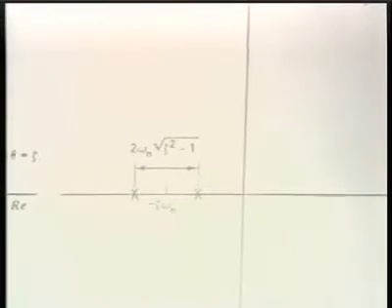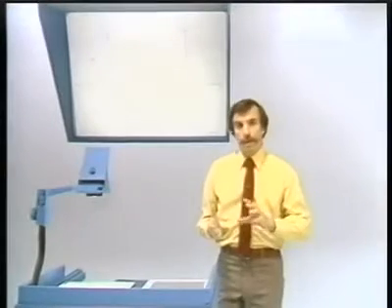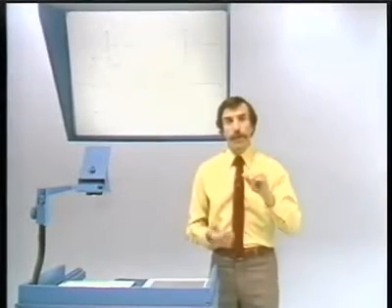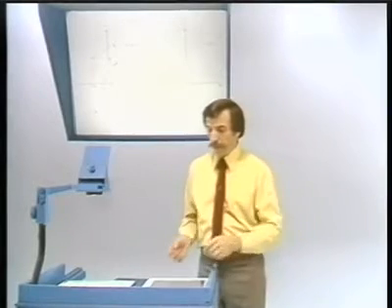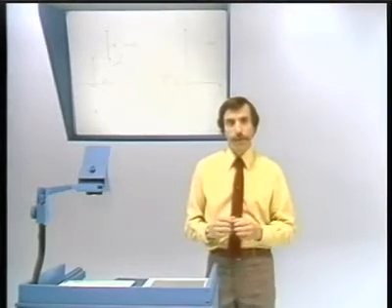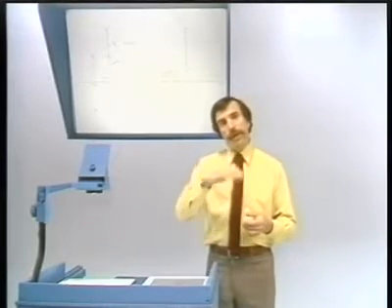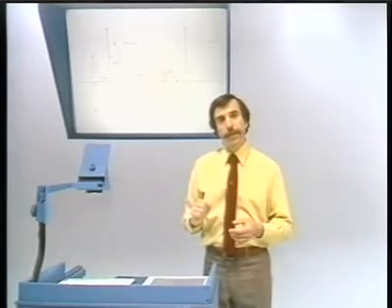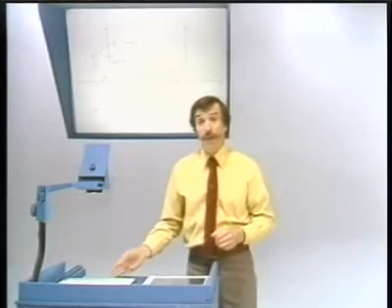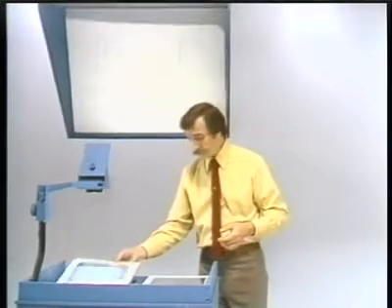Well, actually, the case that we'll want to look at a little more carefully is when the poles are complex. And what this becomes is a second-order system, which, as we'll see as the discussion goes on, has an impulse response which oscillates with time, and correspondingly a frequency response that has a resonance.